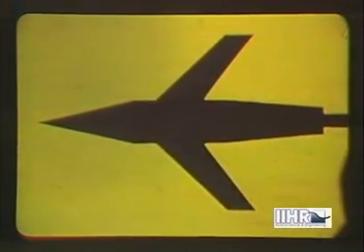A supersonic plane must be so designed that the shock waves produced by fuselage and wings are of minimum intensity, since they give rise not only to the drag of the plane, but also to the disturbance which reaches listeners as a sonic boom when the shock wave passes them. The effect of the swept-back wings is clearly seen as the plane model is rotated about its axis of symmetry. Every shock wave that the Schlieren process makes visible is the source of both drag and noise, and everything possible must be done to reduce the wave magnitude and thus increase the efficiency of supersonic flight.